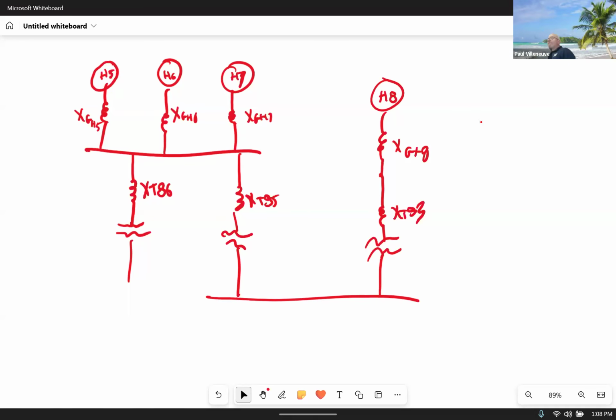Yes, sir. Good question. So would vacuum breakers work at really high voltages? Yes. If you could pull a perfect vacuum, right, where there was nothing in there whatsoever, then it would work. The problem is that the amount of energy, and this has to be sealed, right? So this is under vacuum. So then you got to seal it to keep the vacuum in there. And the amount of pressure, it would leak. It just wouldn't work. So typically what they use after 35 kV, they use sulfur hexafluoride.